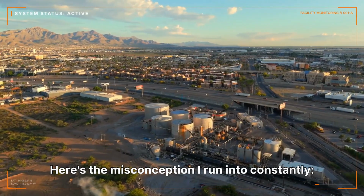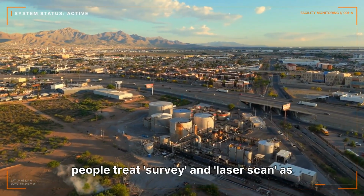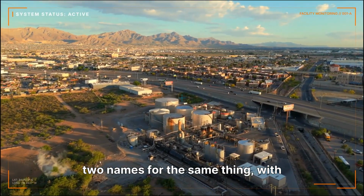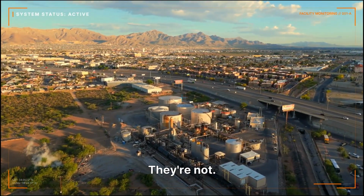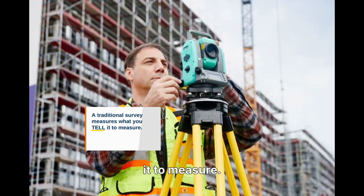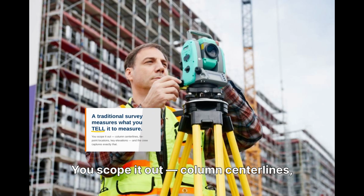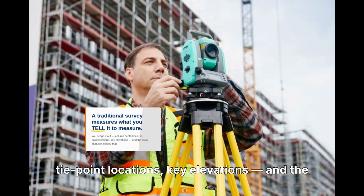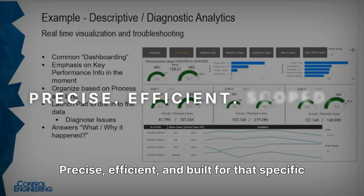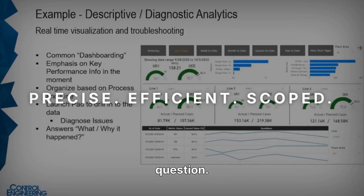Here's the misconception I run into constantly. People treat survey and laser scan as two names for the same thing, with different price tags. They're not. A traditional survey measures what you tell it to measure. You scope it out, column center lines, tie point locations, key elevations, and the crew captures exactly that. Precise, efficient, and built for that specific question.